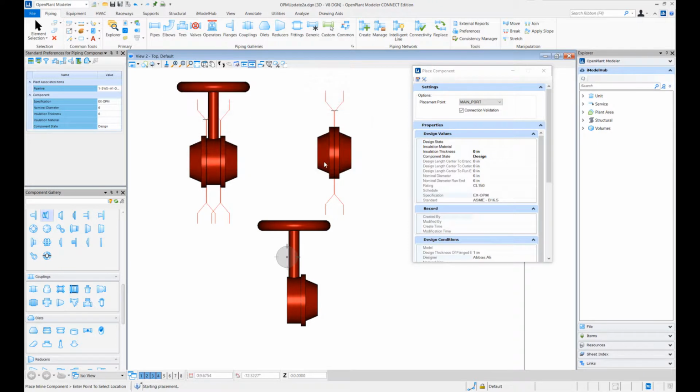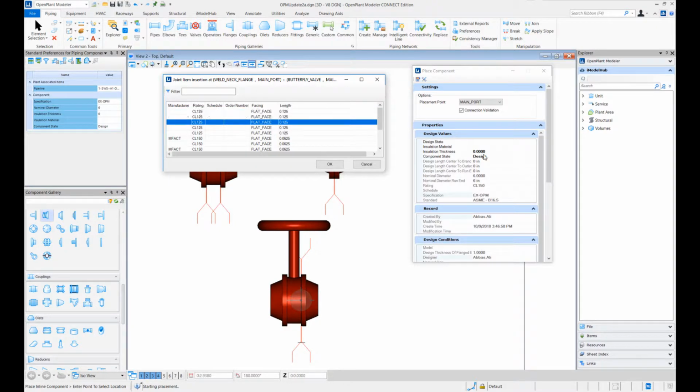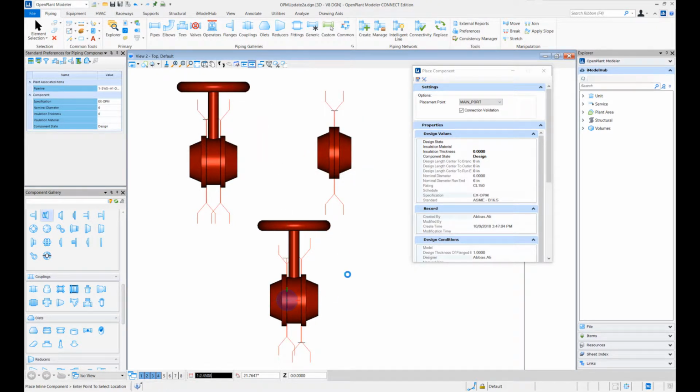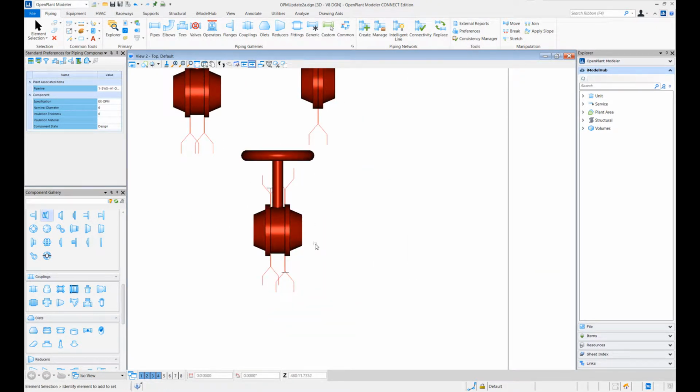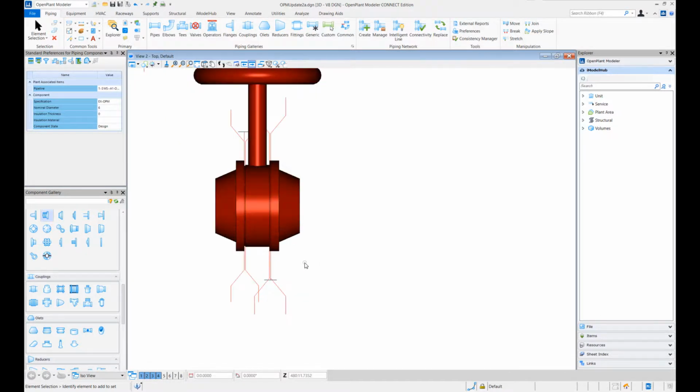And we are asked for selection of gaskets and fully threaded machine bolts at each end. This is a regular behavior of a lug joint that you have. Although the component is a sort of wafer in nature, when you connect it with mating flanges, fully threaded machine bolts are inserted at each end as well as the gaskets.